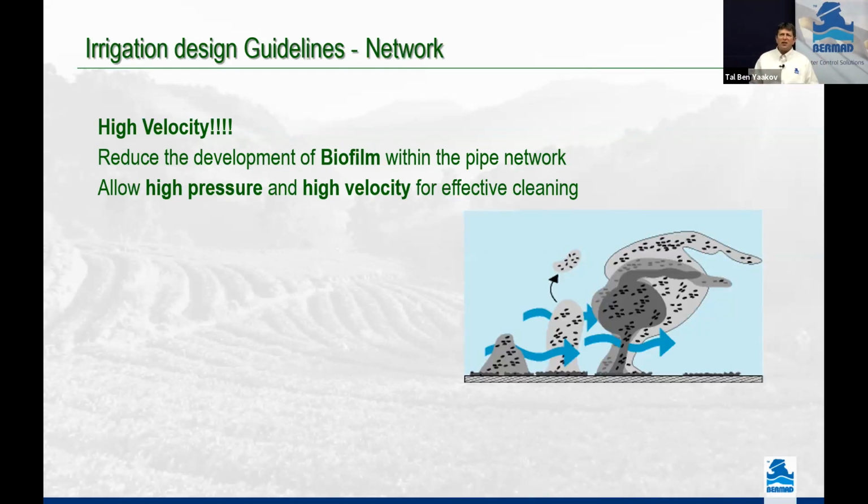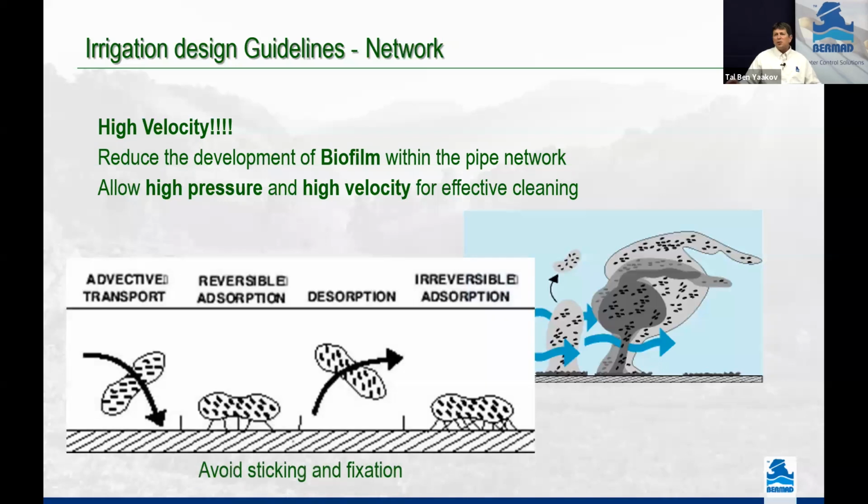In the filter, I want all the dirt to accumulate in the filter and then I can flush it out. Here, I cannot let it accumulate in the pipe because I have problems. So I want the water to move quickly, so that I can flush it out of my system. So this is an important point: I want high velocity to take it away from the system.